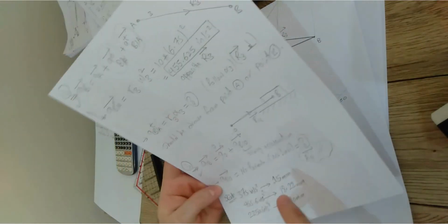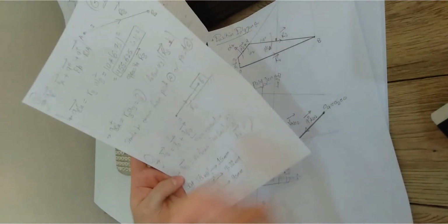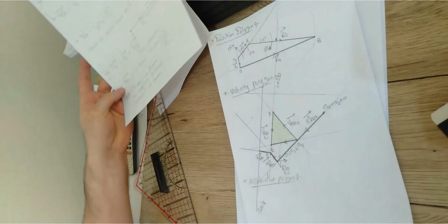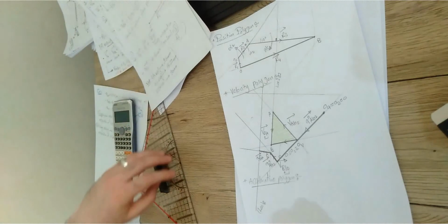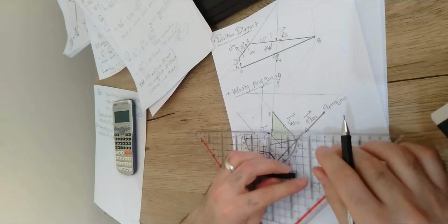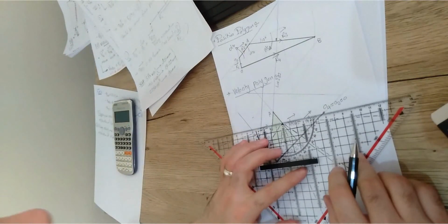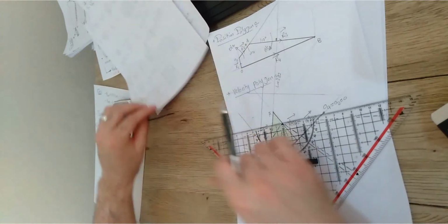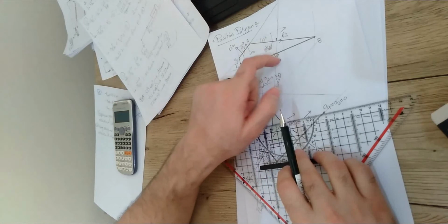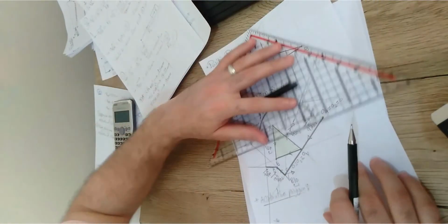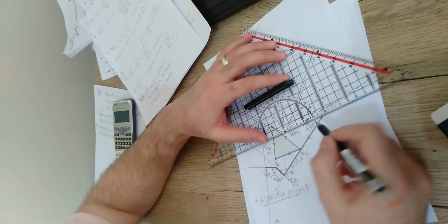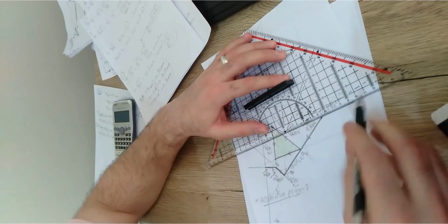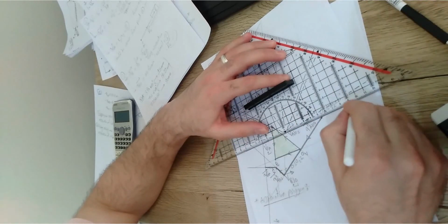It means that this line is going to give us a locus, a second locus to the point B. The intersection of this locus with the locus that we got from the previous equation, we're going to end up with point B. We can locate this point B. So what I'm going to do, I'm just going to draw a line parallel to the R4. And R4 is horizontal. It means that you're just going to draw a horizontal line from this point O. I'm just going to draw these two lines with the red color.